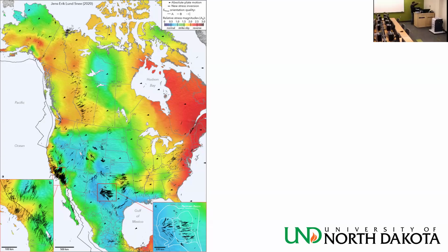Dark blue for 0, dark red for 3, everything else in between. So green will be 1.5. And I will color them up according to the stresses. So where I have blue is normal faulting, where I have green is strike slip, where I have red is reverse faulting, and I have all the color spectrum in between.